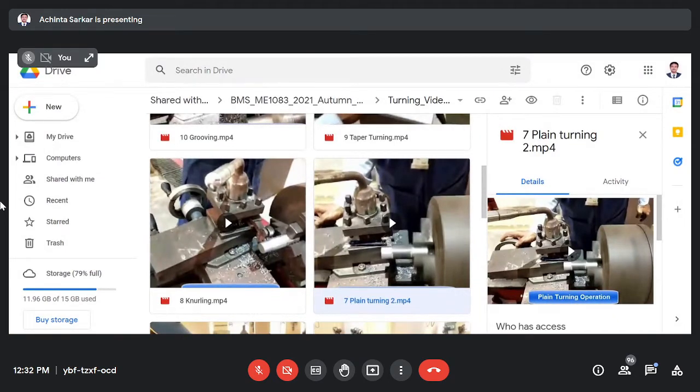Then upon 1000, again one constant is coming. So pi DN upon 1000 can be expressed in meter per minute, because it is divided by 1000. Okay, so it will be meter per minute. This tangential velocity is also an important factor, because if I put the optimum cutting velocity, we are going to get a good quality job along with good